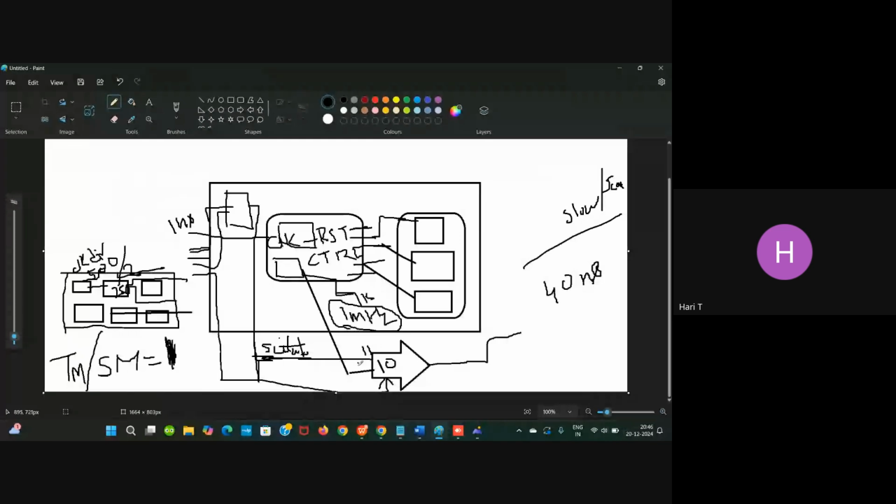There will be n number of muxes in the design where they will be bypassing in this scenario. So what the designer does is connect this selector line to scan mode. I1 will be a suitable clock frequency which is available for DFT testing. I0 will be a random clock frequency which is used for functional test. That is the reason behind every mux's selector line being connected to scan mode.